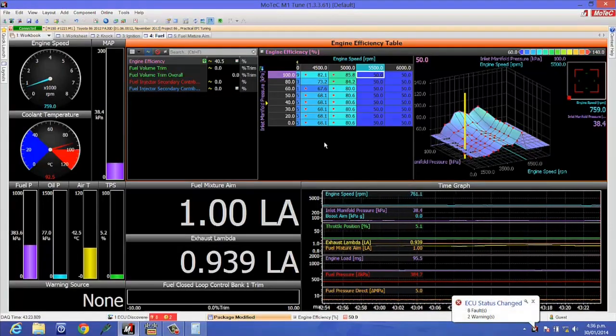At higher RPM, this process can put a lot of stress on the engine, and we may also find it harder to control the engine temperature. The reality is nobody ever really drives their car at part throttle and 6500 RPM for extended periods of time. What I mean by this is there are certain parts of the fuel map that we don't need to be quite so accurate about. My rule of thumb is to use steady state tuning up to about 2/3 of the rev limit RPM. In our example, I'm going to tune to 5000 RPM in steady state.